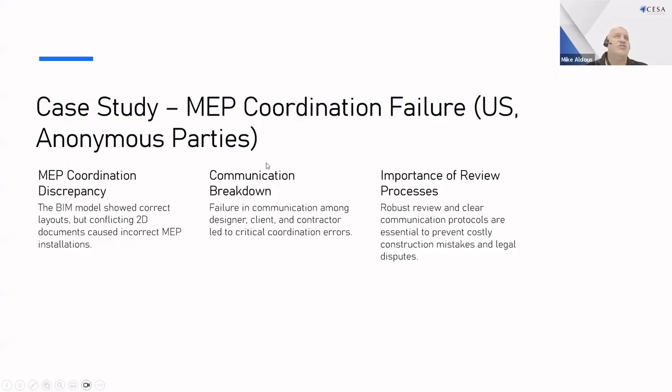So this goes back to my previous point around communication, is making sure that just because it's BIM doesn't mean it's right. It needs to be right in the model, but it also needs to be correct in the information issued to site. What we're seeing on some projects now is that the actual model gets issued to the contractor, and the contractor then develops their own effectively construction response to that. However, the more common delivery is still to hit the contractor up with a set of drawings derived from the BIM model rather than actually hand over the model itself.